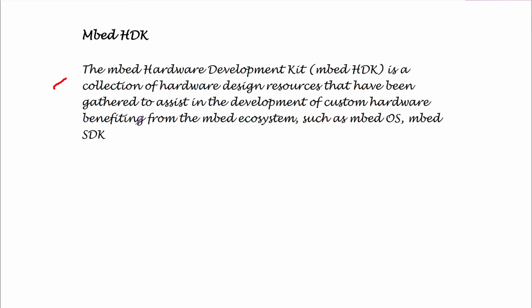You can have different components on that board. You can create a layout. You can create the schematic, just like the manufactured boards. So the HDK provides all the resources so that you can design your own hardware instead of relying on a particular or specific manufacturer. In this way, if you are making your own product or prototype, HDK is very useful because it will allow you to have only those components which are needed for the project. You don't have to unnecessarily use other components which are a part of the board.